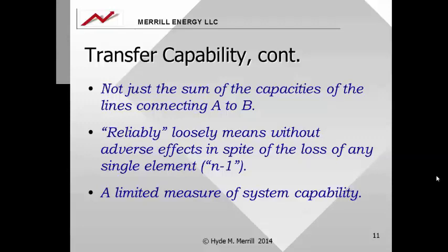In addition, the transfer capabilities shown on the diagram of the previous slide are non-simultaneous. That is, they can only be considered one at a time. For example, the 1100 megawatts of incremental transfer capability between ECAR and MAC assume that the transfers among all of the other systems are fixed at their base conditions.